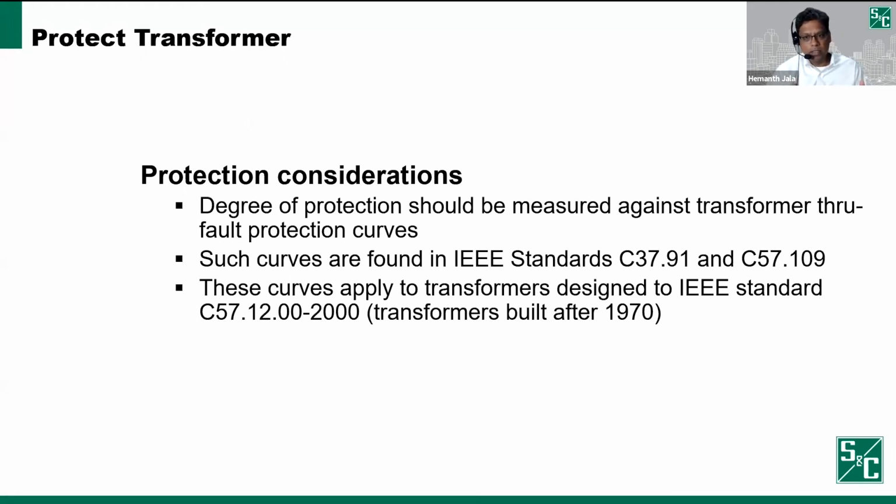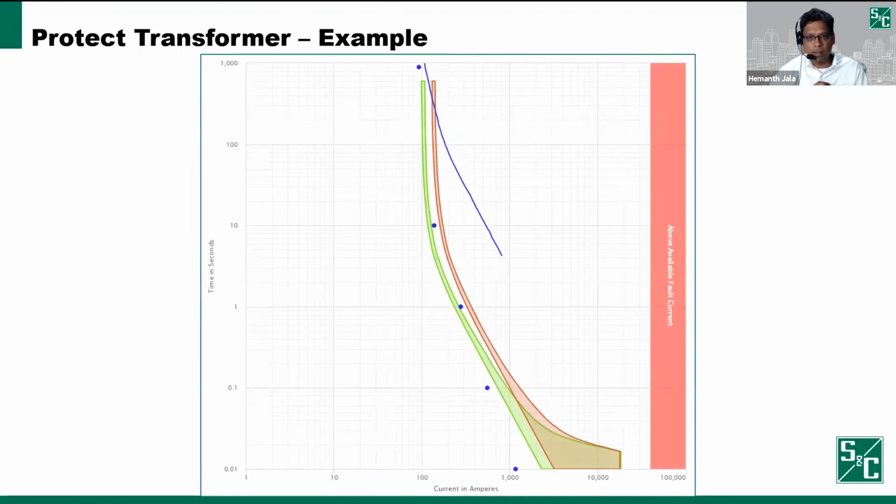What you want to do is select a particular transformer and select a fuse based on the application factors that you looked at. You make a decision on which fuse to use based on how well it protects the transformer and how well it handles the transformer inrush and any other continuous current. For that, I'd like to use an example, which is up on this page.